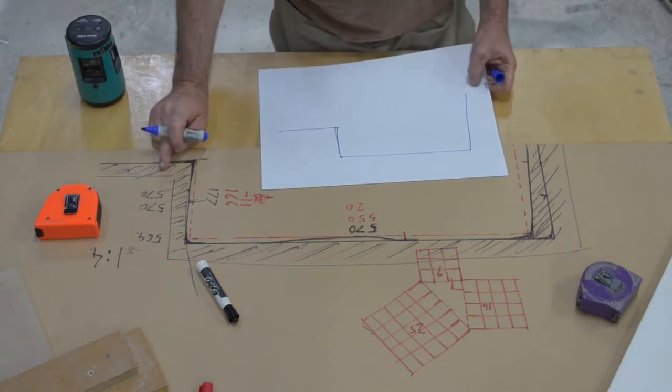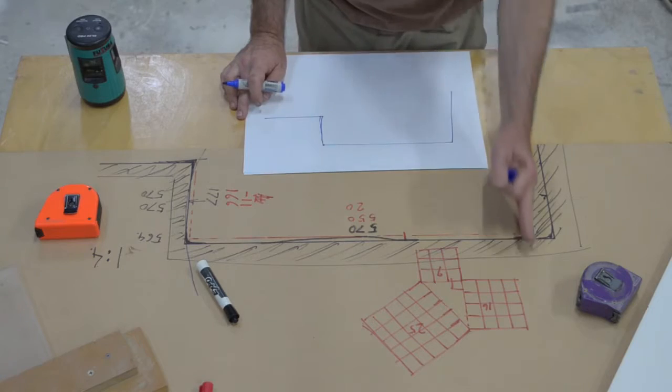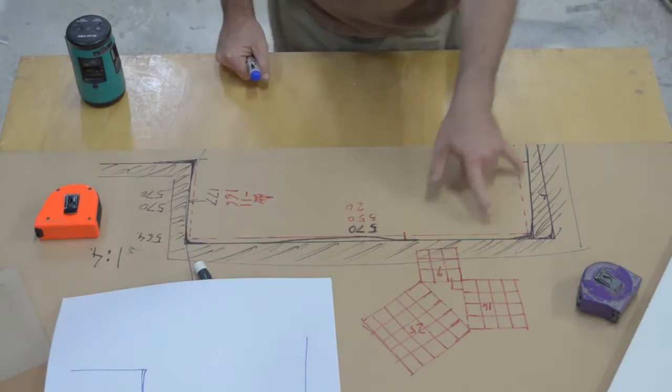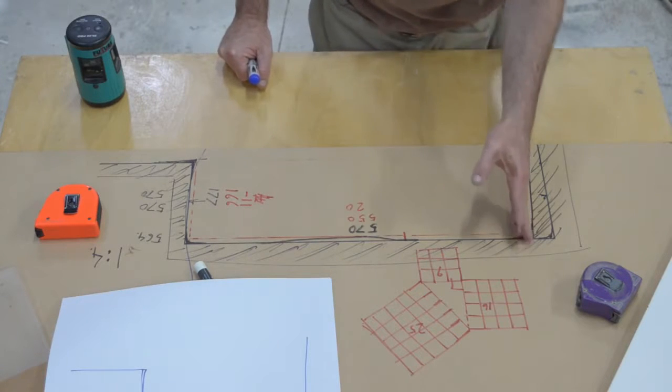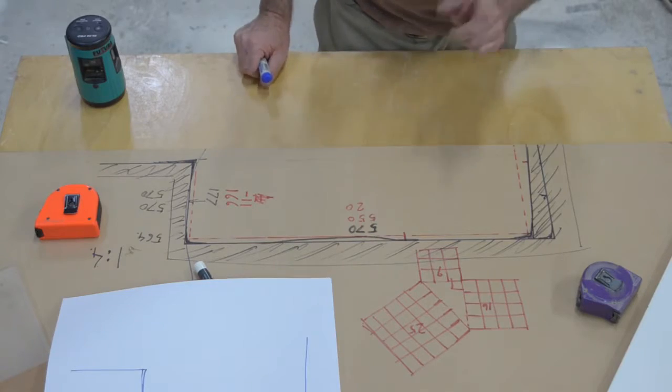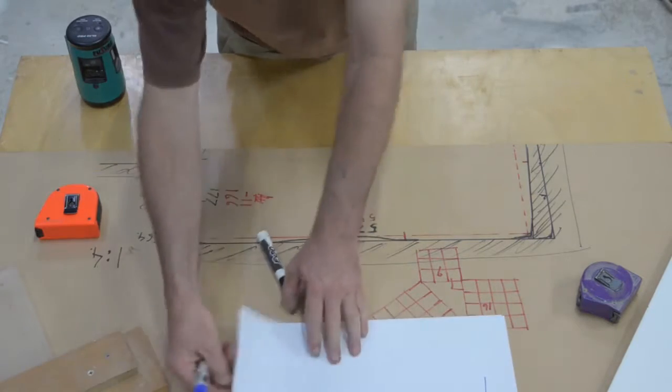If you like, you can do that. If you've been able to generate a square line, which we can do with the laser, or we could do with Pythagoras, we could create this square line out from that back edge. That's an alternative way. In fact, I might demonstrate that too before I get too carried away.